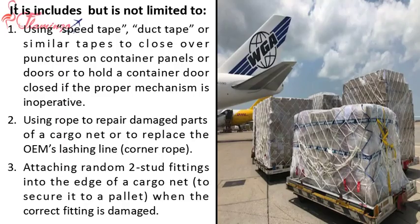It includes but is not limited to using speed tape, duct tape or similar tapes to close over punctures on container panels or doors, or to hold a container door closed if the proper mechanism is inoperative. Using rope to repair damaged parts of a cargo net or to replace the OEM's lashing line, corner rope. Attaching random two-stud fittings into the edge of a cargo net to secure it to a pallet when the correct fitting is damaged.